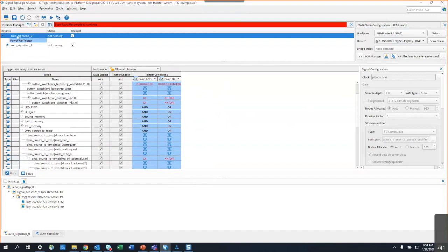So that way you can see what happened after reset, but before I was able to start the logic analyzer. My experience when I was an FAE was this was very useful when PLLs weren't locking and such, because that happens before you can ever hit the point where you'd like it to trigger. So this is a good way to debug that. Yes. Okay.